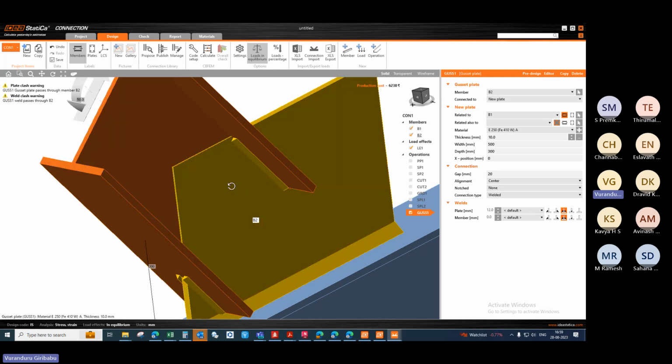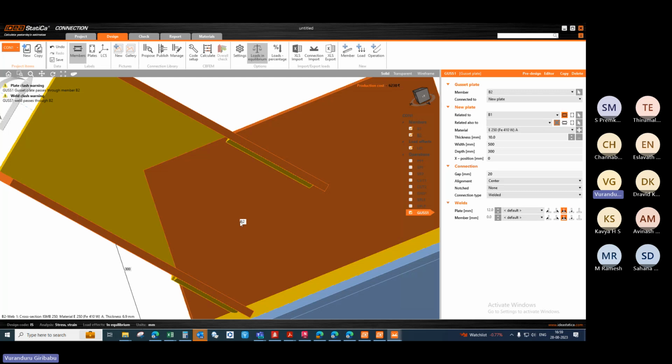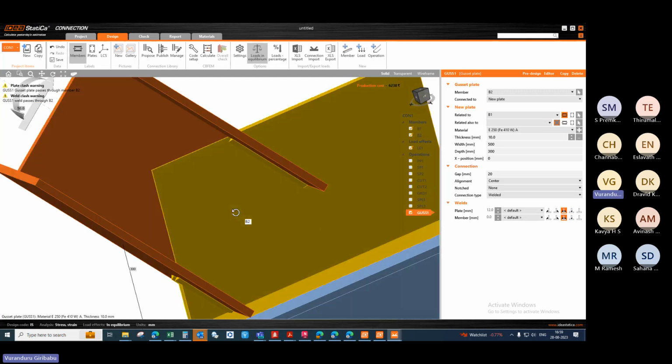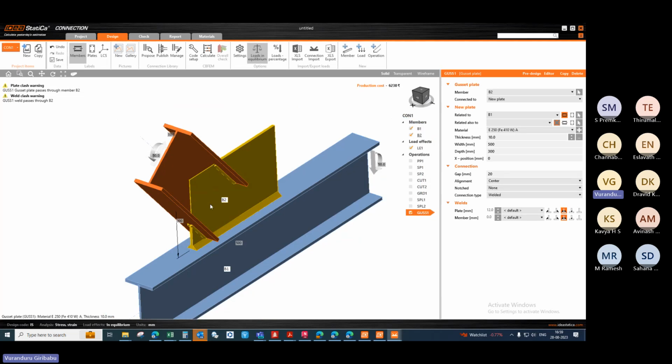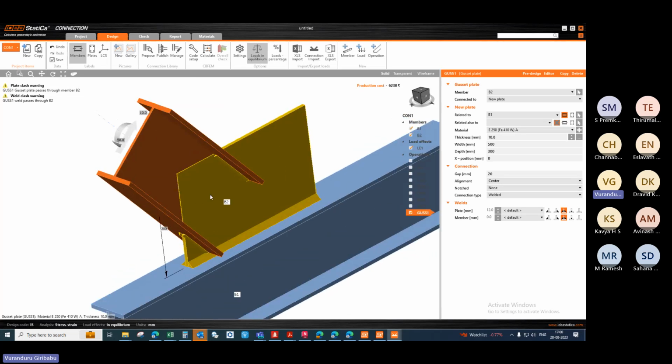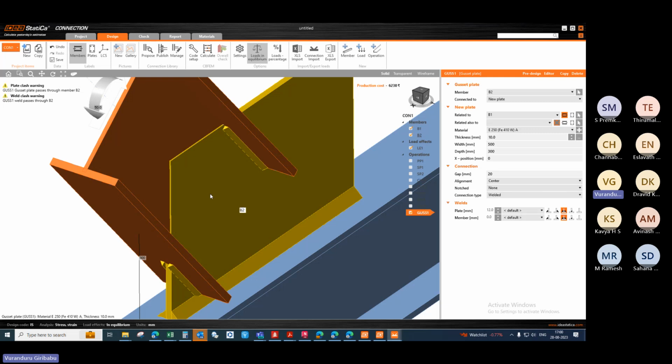In that case you have to be in center only. You have to put this plate, and again you have to put one more plate on both sides, and you have to weld a bolt to these three plates. One side you can weld, and on both sides you can bolt it. So in that case it can be exactly in the center, but it is not required to be that much in the center. We can have it opposite any side of the web.